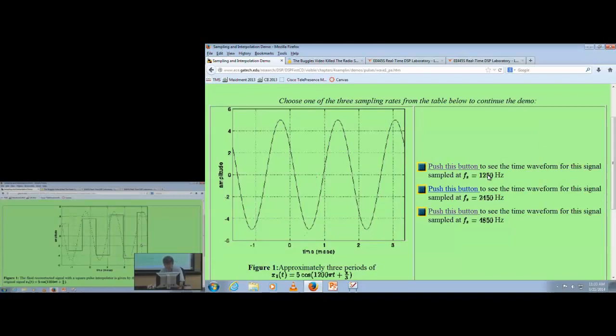And it doesn't look all that good, honestly, at least in the time domain. But it does capture the significant frequency content, which is reflected in the zero crossings. So for a sinusoid, we want 2 zero crossings per period of the cosine or sine, and we get that. They don't occur in the right locations, but they occur with the right frequency or the right rate. Now, in practice, we could clean this up with an analog low-pass filter, and that would round out the edges, at least for any frequencies at or above half the sampling rate, but we'd still have some harmonics that would get through.